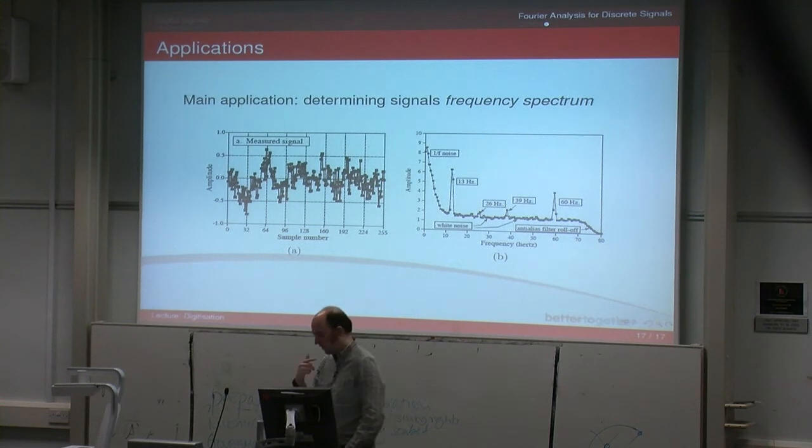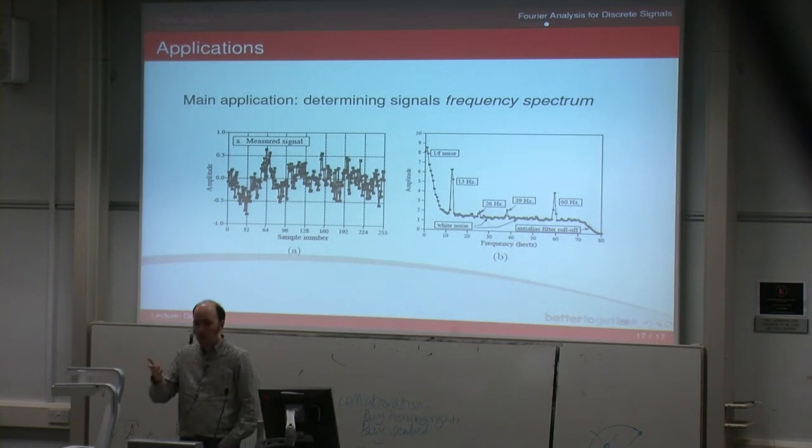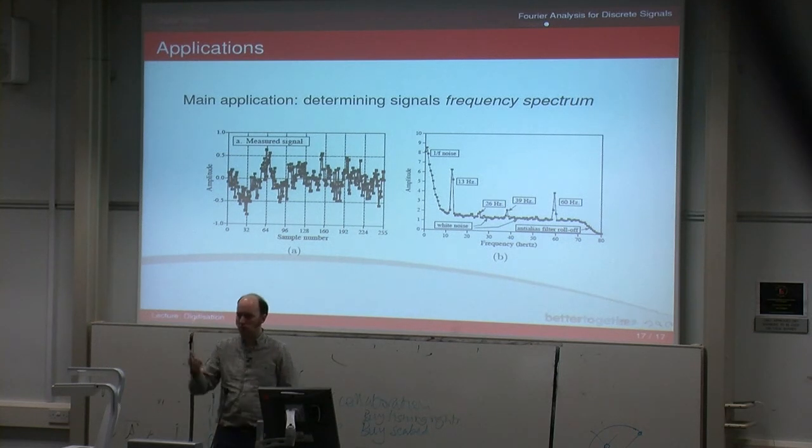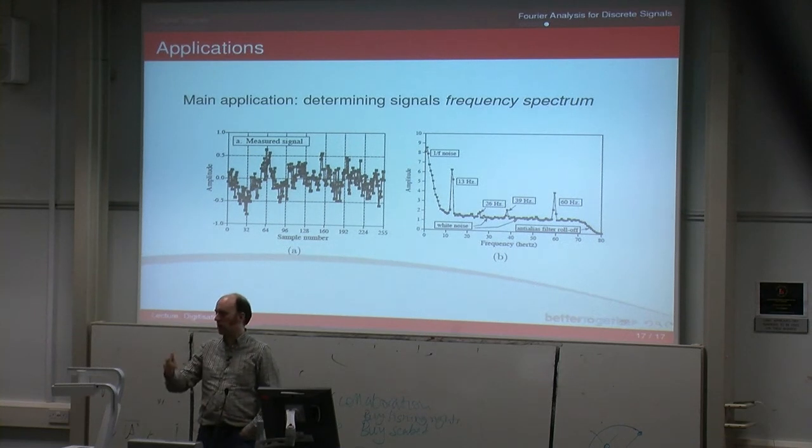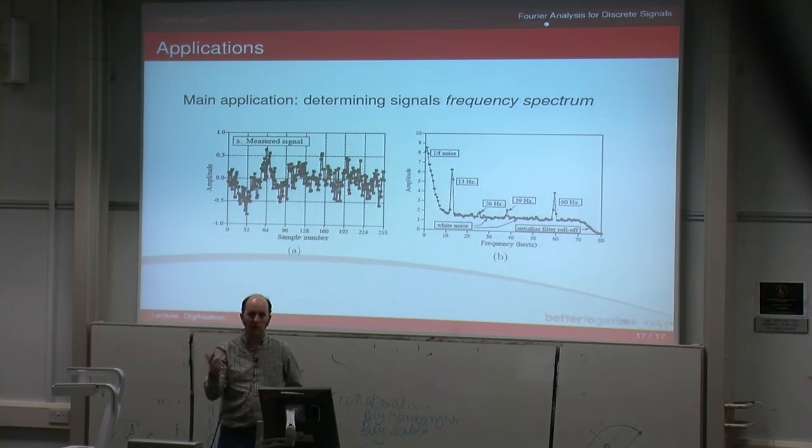So say you're using the Cortical rig in the dynamics lab, measuring the motion of the structure based on a road input. You might have to make sure that your sampling rate is twice the frequencies that you're going to be looking at, or fast enough.